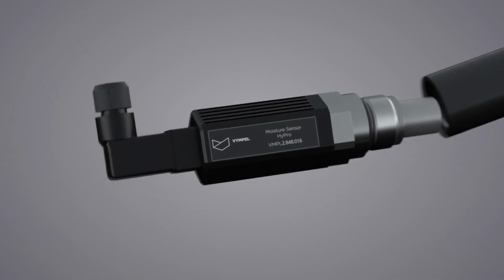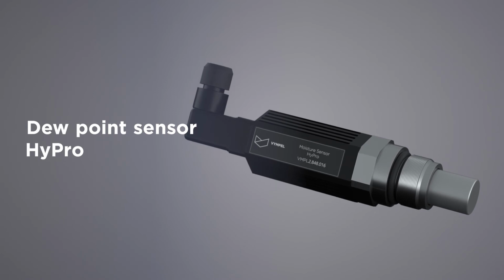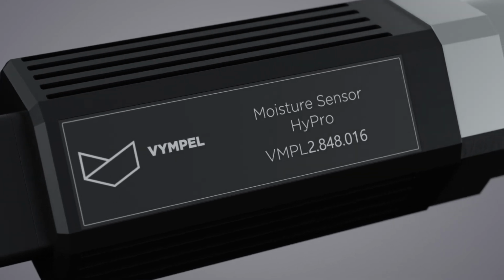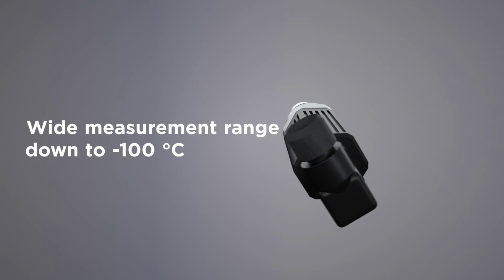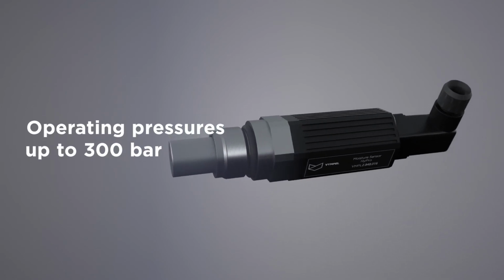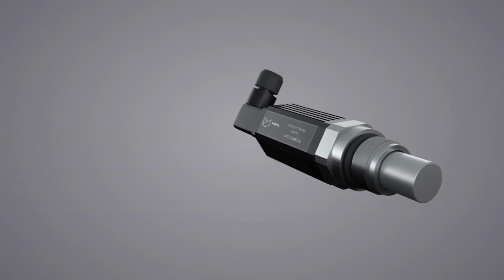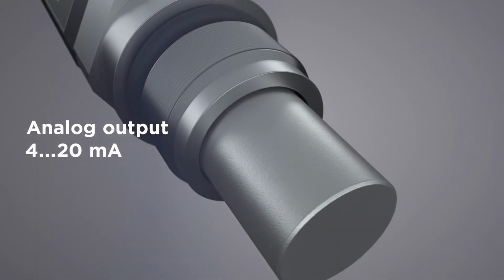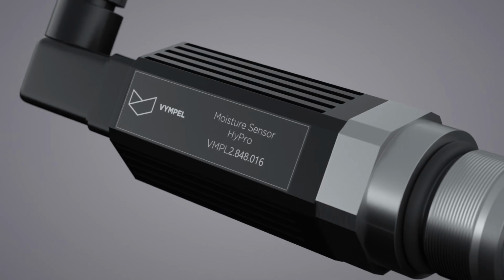As a supplement to its range of unparalleled chilled mirror dew point hygrometers, Vympel has developed the HyPro sorption-type moisture sensor. The HyPro is designed to measure the water dew point at temperatures down to -100 degrees Celsius and at operating pressures up to 300 bar. This sensor is designed mainly for measuring the moisture content in inert and aggressive gases, including those containing hydrogen. HyPro sensors are also an ideal choice as a cost-effective solution for natural gas treatment processes.